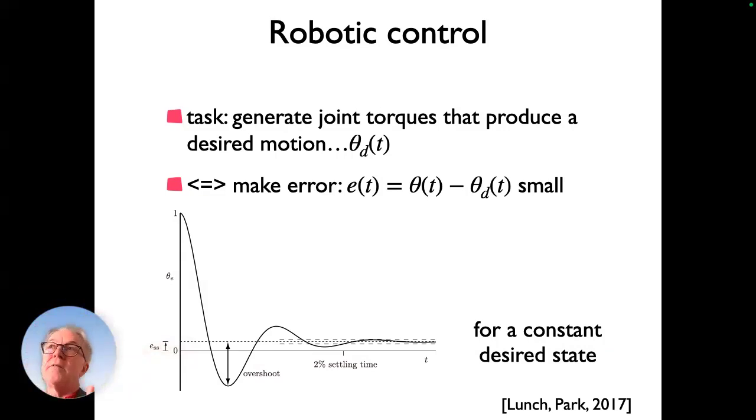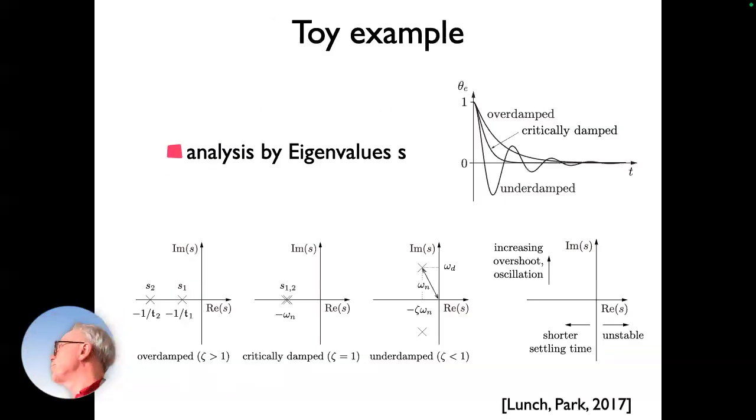In practice, it will tend to lag a little bit behind, and it might have a little bit of an oscillatory component, like a little overshoot, and there's some damping until this overshoot is taken away. You can imagine that limits how variable in time your desired trajectory can be. You can't have a very rapid trajectory if you're lagging behind too much, right? So the position of that control determines how rapid the movements are that you can impose, that you can actually follow.